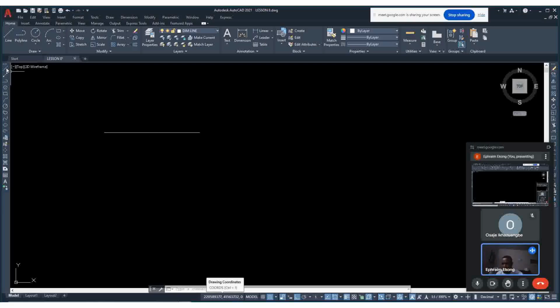So we have to create this arrowhead. To create it, we can offset. Pick a line here and click at this point. Take your cursor this way, then type 200 and press enter. End your command. So this is 200.